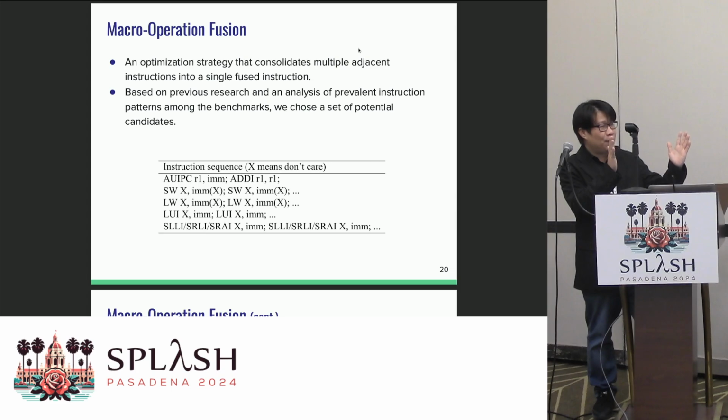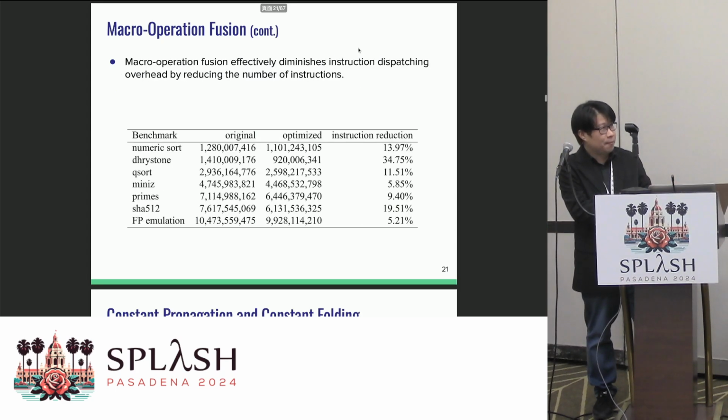So we can combine several RISC-V instructions into a single instruction. Like this, we have found several patterns, so we will just provide the smaller counterparts, meaning that we can eliminate the instruction dispatch overhead. And from the preliminary benchmarking, the technique is quite useful.